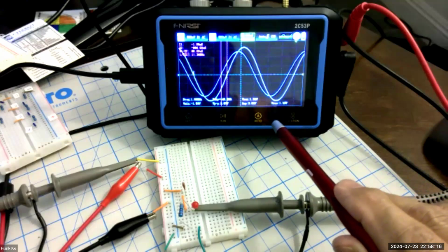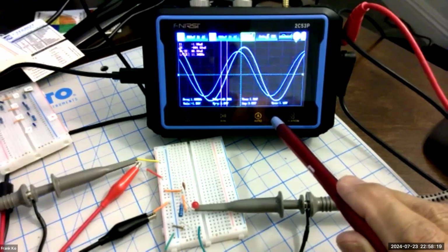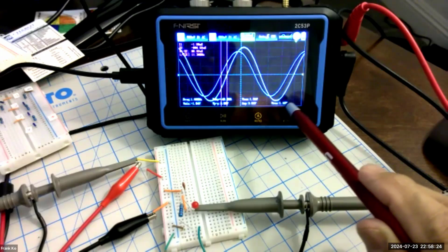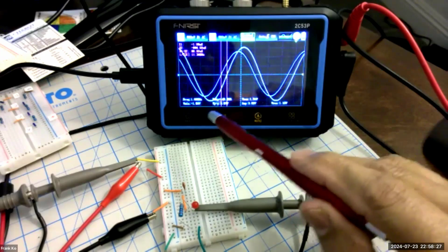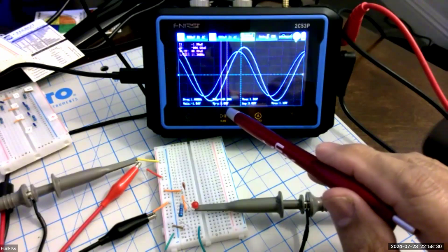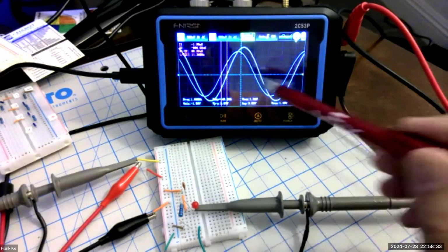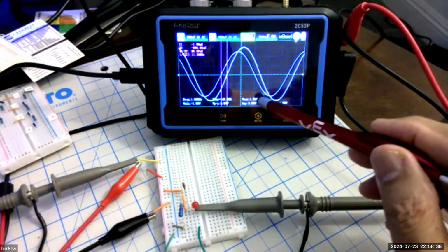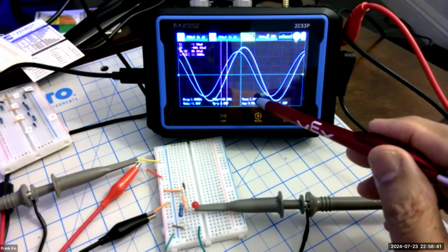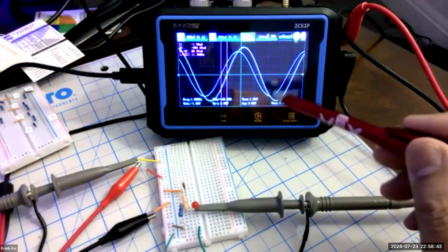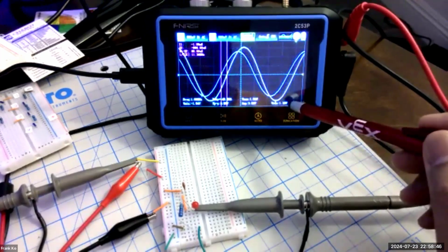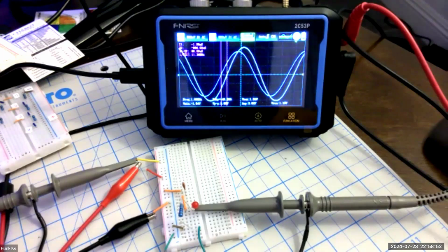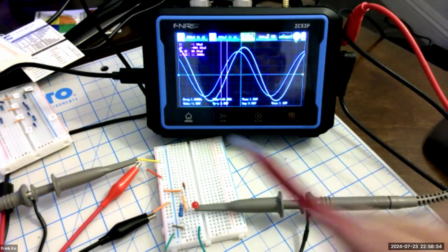We had approximated based on the peak voltage that the RMS works out to be this value. So there, at 500 millivolts per division, so roughly 1.5 volt peak. And my 1.5 volt peak, as you can see, well, you can't see here, but take my word for it. My volt peak is at 1.54. And if you multiply that by 0.707, you're going to get something very close to this displayed 1.10 volts RMS. So this works really, really well to give you this information.